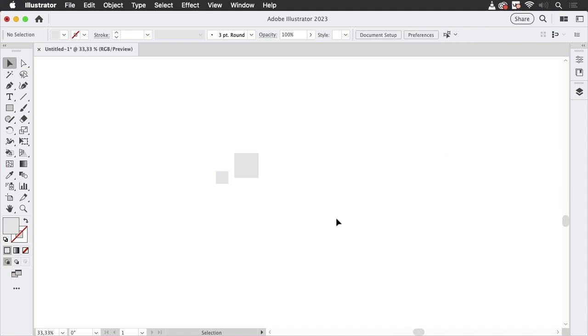There's one important thing to note with the selection tool though, and with moving. In order to get the transform tool smart guides working when moving objects with a selection tool, what you have to do is press Command or Control on Windows, and you see now you have the lines. When you don't press, you don't have the lines.